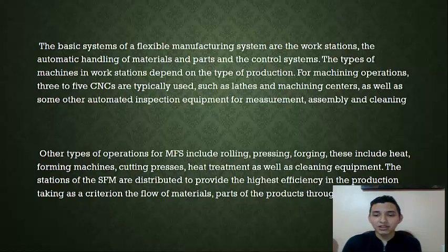There are three ways to pass the piece through the machining positions: keeping the sequence, in sequence with the possibility of omitting some positions, or in free sequence. There are also two forms of transportation and fastening: with pallet and without pallet.